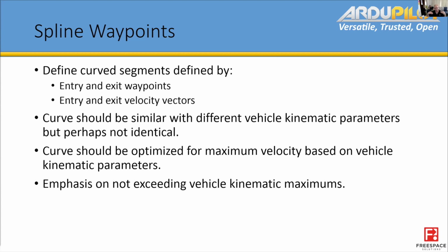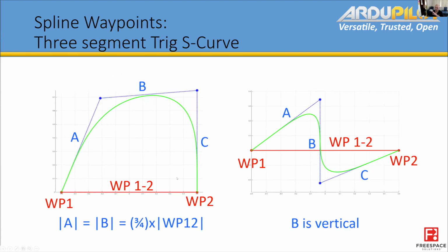We should never exceed our kinematic limits specified, you know, WP_NAV, max accel, things like that, or max jerk. This should be twitch free. So these are a couple of examples of how we ended up calculating these things for the S-curve based implementation.